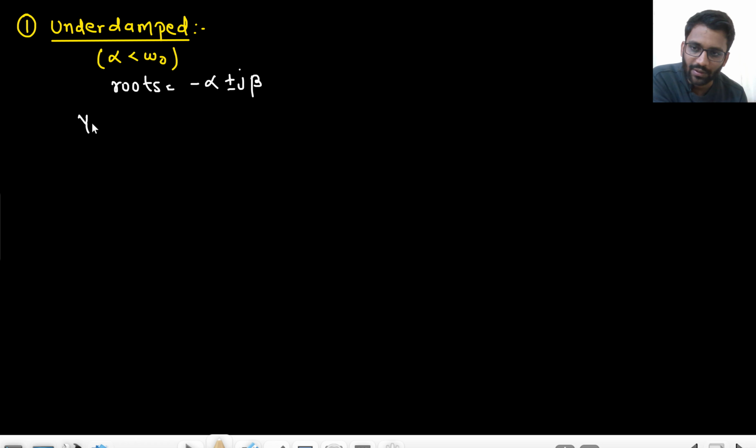So simply, what will be my y of t? My y of t would be y of infinity plus e to the power minus alpha t times (c1 cos omega d t plus c2 sin omega d t). The roots are alpha plus minus j omega d.